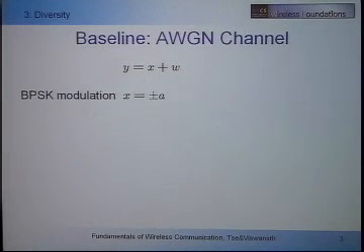Okay? So let's go through the most simple example. You send a BPSK, more jargon, sorry. Binary phase shift keying. Communication engineers want to be their own club, right? They don't want to admit people. So they make very complicated terminology for a very simple idea. And the idea is you send plus or minus A, and they call it BPSK. Four letters for one bit of information or less. Plus or minus A. All right, so it's one bit of information.